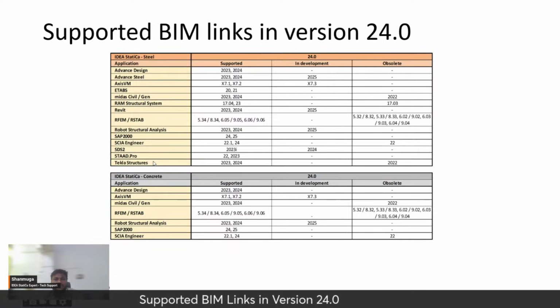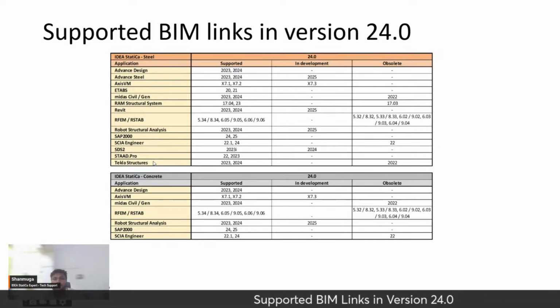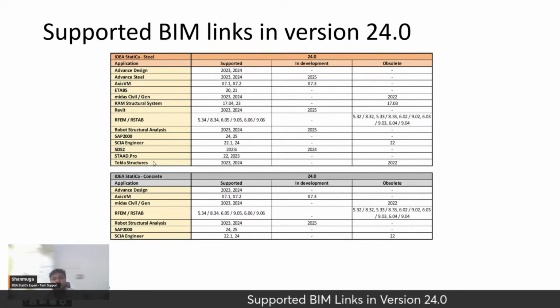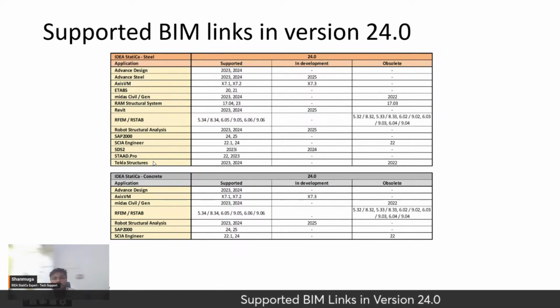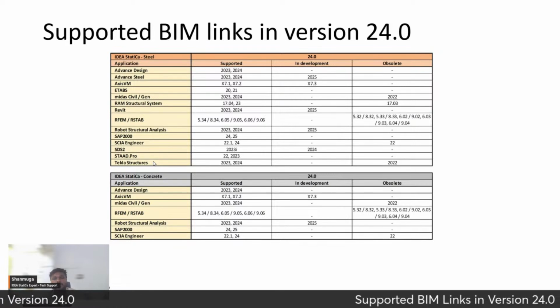Suppose you are using design software like STAAD.Pro or ETABS, we can bring in the connection geometry as well as the load application and load combinations into the software. We use the operation connecting the members from the imported geometry from the design software, and then we perform the connection design. So these are the versions supported by third-party applications, which are very compatible with IDEA StatiCa software for performing the connection design in a very simple way.